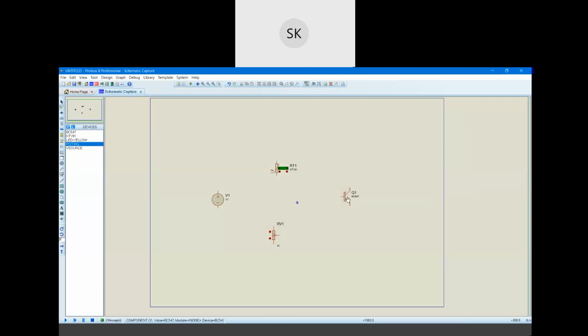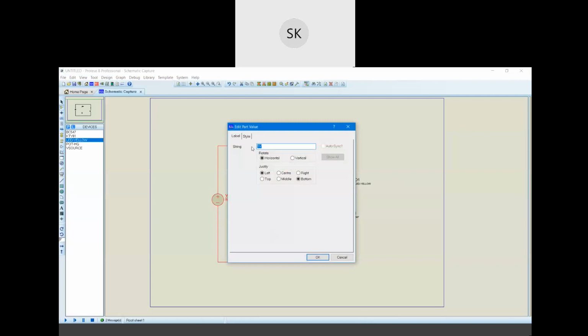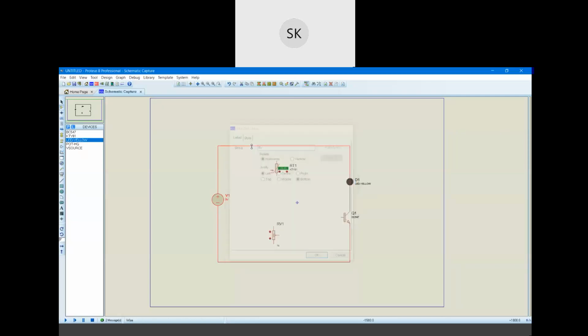What basic things have we discussed? There is a sensor, there is base current, and there is an indicator circuit. So for indication, I am again selecting a yellow color LED. You can take any color. Okay, let's go stepwise. Let's connect this LED to its collector, and emitter to ground. It is again this, and I will increase its value to 9 volt.